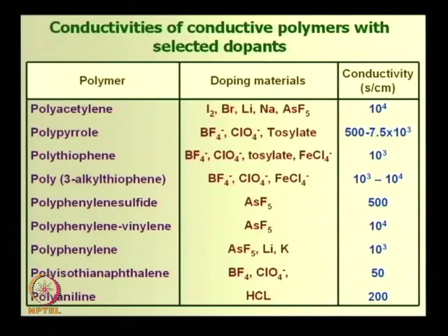There is heavy power loss, energy loss while it is transmitting. Now, that power loss could be minimized, we can save money if that power loss is not there, if there is no resistance. Since there is resistance, we are getting this power at low voltage here, but for getting power at this low voltage, we have to transmit from there at such high voltage, otherwise one cannot get it.